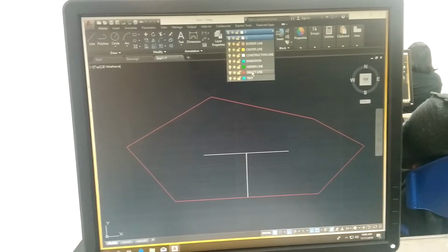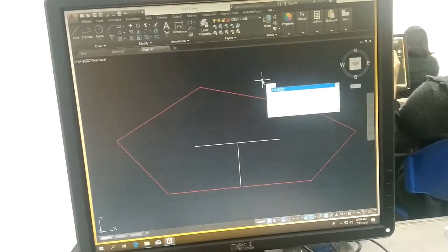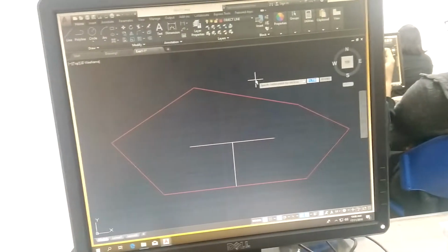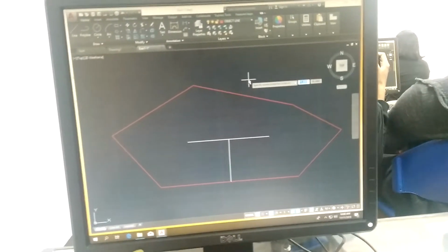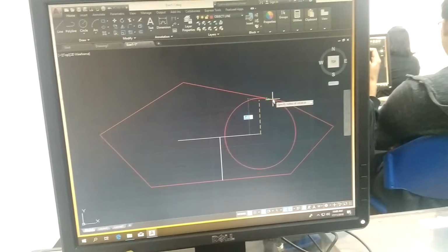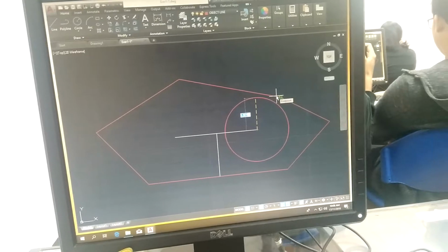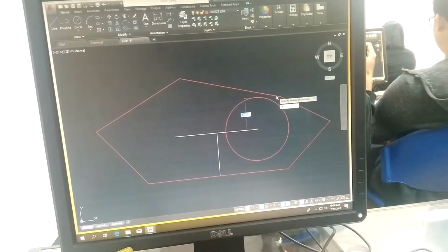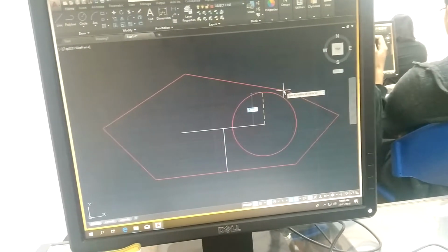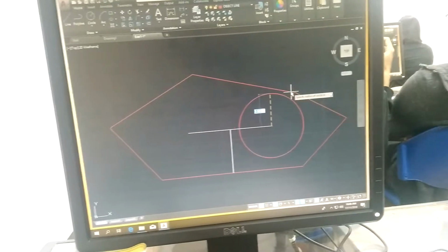I'll go to object line and draw a circle. Okay, command circle or C. Enter. Specify center point. So drag it. Now the circle command has only one option by default, radius. If you press the arrow down, there is another option. But since in your model the given is radius or R, there is no need to change the unit, just enter 0.5.